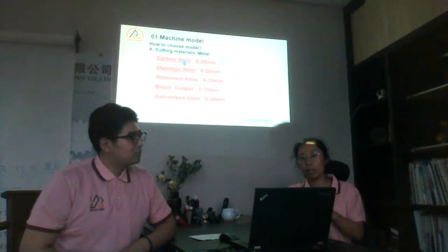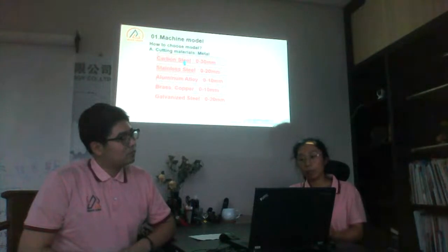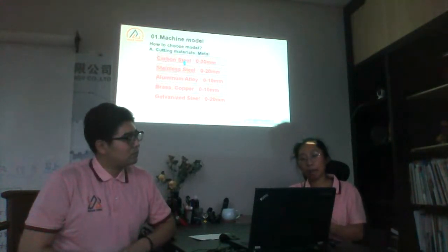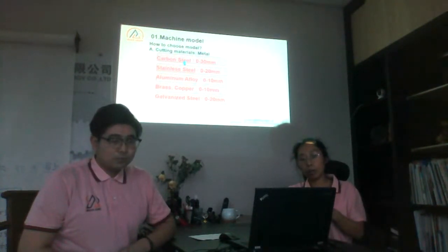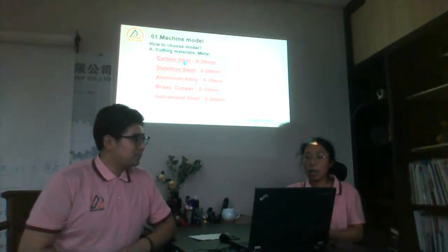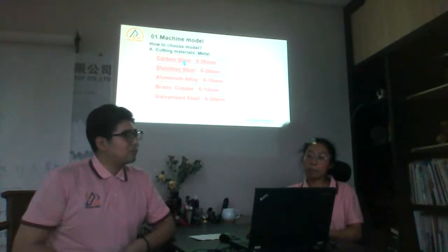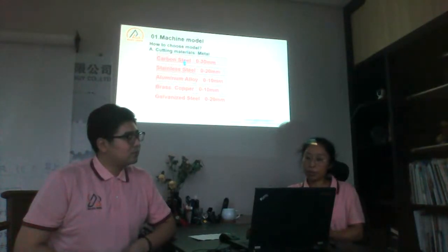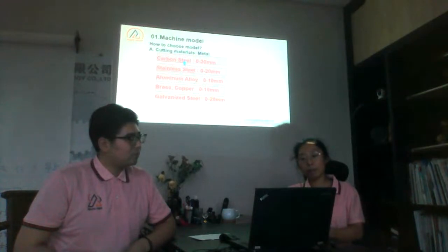Our laser cutting machine is mainly cutting metal, and different materials have different cutting thicknesses. The size of the carbon steel is about 0 to 30 millimeter, and the stainless steel is about 0 to 20 millimeter.